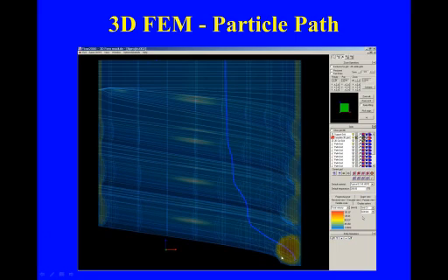So here's the first one. I've started from this point right here, and you can see how the material flows through this flow field and comes out at this point here. Now what we're going to do is put a series of points around that inner wall of the starting point. If we follow those points around and connect the dots at the exit, we'll have an idea of where the material from this inlet ends up at the die exit.